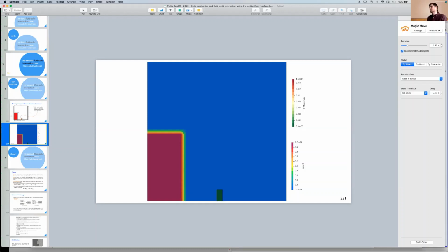Typically in OpenFOAM you use the 6 degree of freedom solver to do rigid body. So you could have 2 different parts and use a 6-DOF solver, and then for your elastic part use Solids4foam or a similar solver. You may require some coding, I'm guessing. If someone hasn't done something like this before in OpenFOAM, my experience is you may have to get stuck into the code to connect the features yourself.